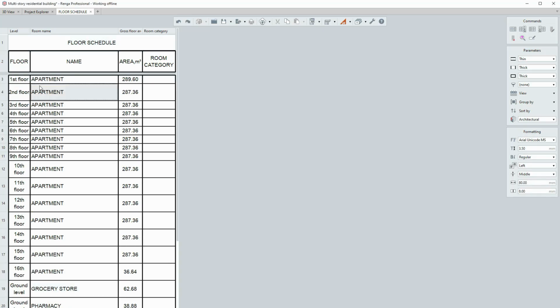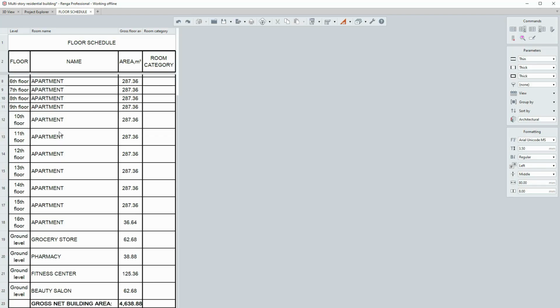Parameters or properties in cells can be edited. By doing this, the data in the model will also change. When data from more than one object is combined in a single cell, the data from all of the objects is updated. To change data in the cells, double-click the cell where you want to enter text. Enter the text. To break lines, press Ctrl+Enter. To finish editing, press Enter. Editing is not possible for all cells. The following data is not available for editing: quantities, data in the cells of the common column, numeric values in the columns when the summarize values on aggregate checkbox is selected.